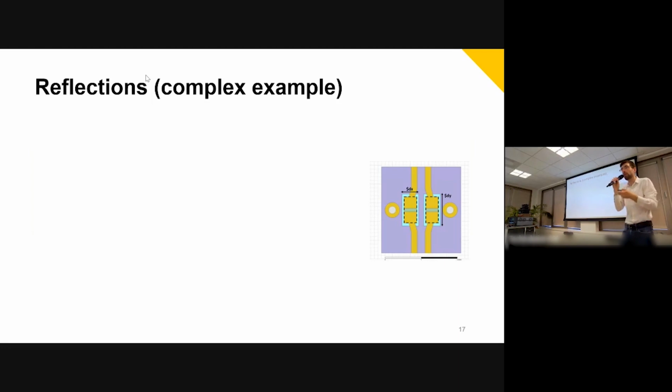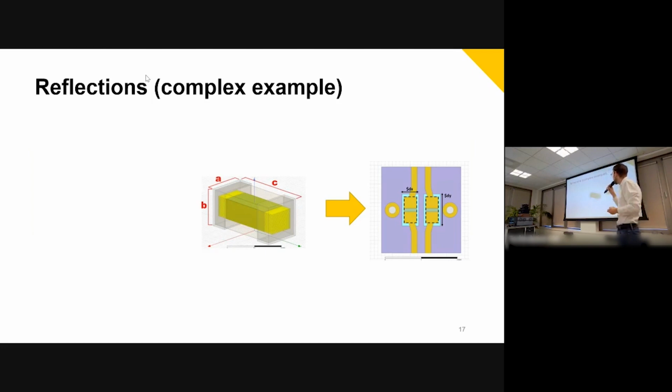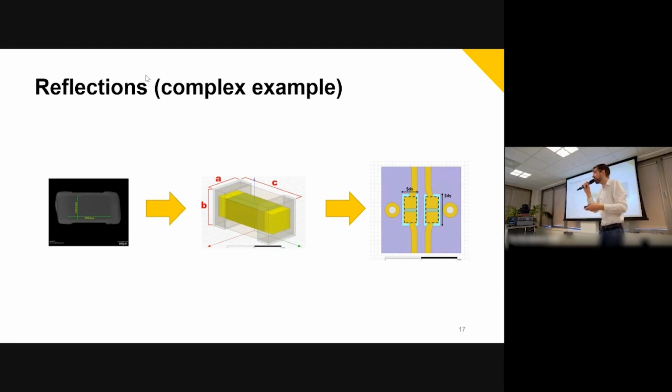One approach, one taken in the example I cite here for 100 gigabit per second, required electromagnetic simulations. But in order for this simulation to be realistic, you also need to know what's going on inside the capacitor. And that structure is the trade secret of the manufacturer of the capacitor. So in this particular case, X-ray cross-sectioning was used to count the number of plates, to extract material parameters, and to create a proper model. They also compared whether this was actually necessary by using a simplified capacitor model, and in this case at 100 gigabit per second, it did matter.